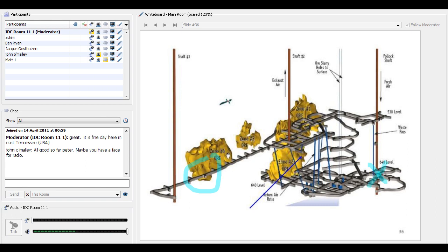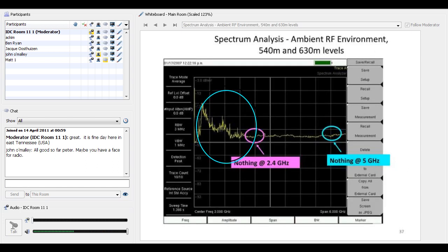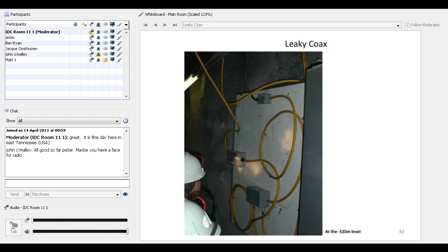Now, distance-wise, this is like 1 kilometer, 1.5 kilometers long, and there's basically no way that you can get your radio signal right from your walkie-talkie to go down this route and then wind up inside his radio. It's not going to happen. So how do you get your communication network to work? Go back. That's leaky cable. So you're going to become experts on, hey, we may use a leaky cable for our communication system. You may have walkie-talkies that have a specific frequency that they use, 433 megahertz tends to be it, and they talk through this crazy cable.